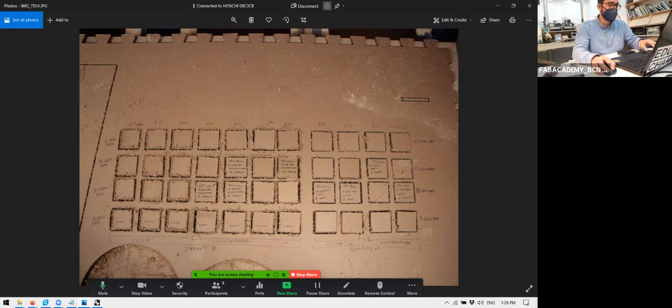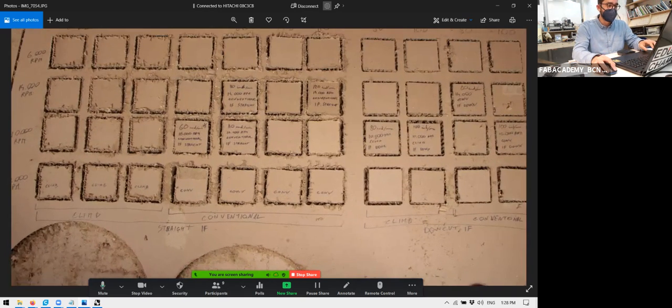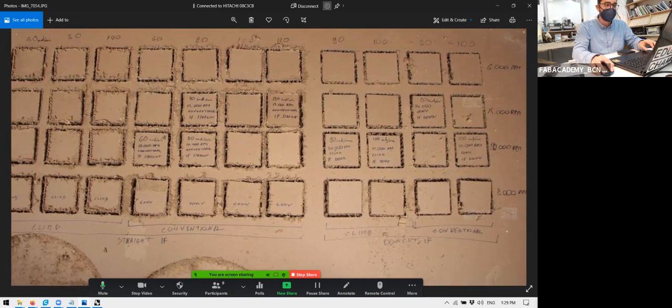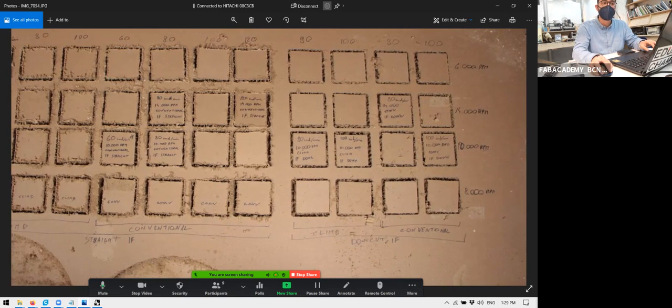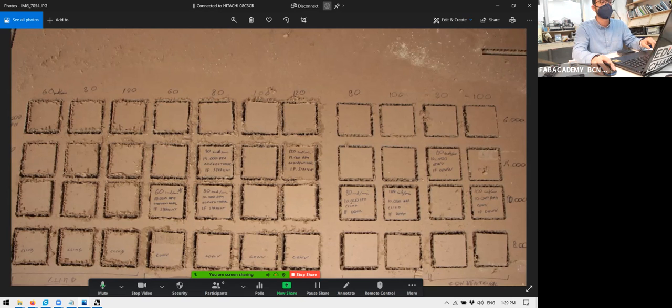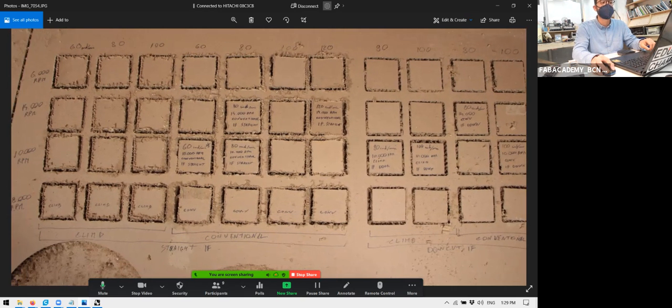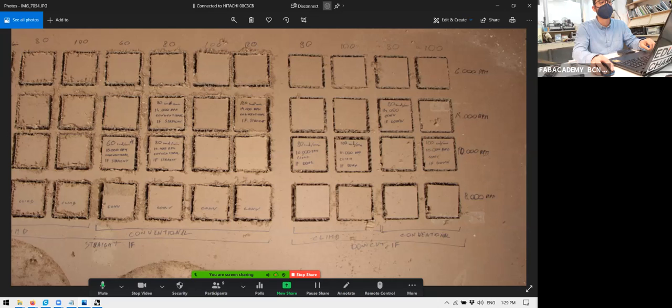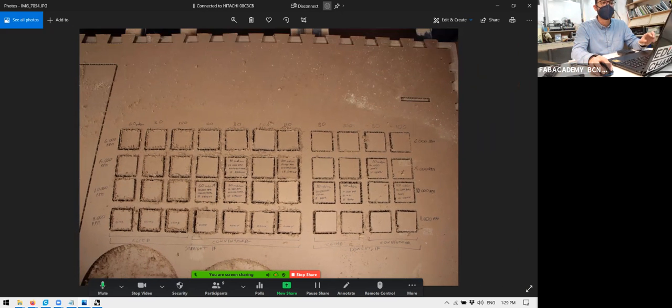For example, this is using a straight cutter, one flute, down cutter, one flute, ranging from 8,000 RPM to 40,000 RPM at feed rates of 60 to 120 inches per minute. Basically, you make charts, and these ones were the chosen ones, and then another test with the final ones to see which one gets better. This is what you need to do for the group assignment.